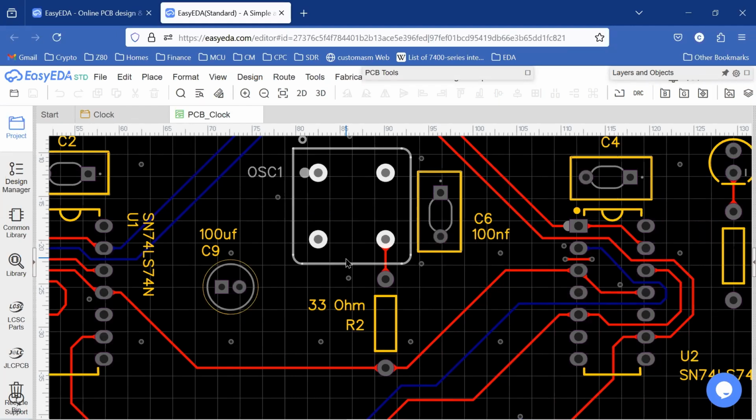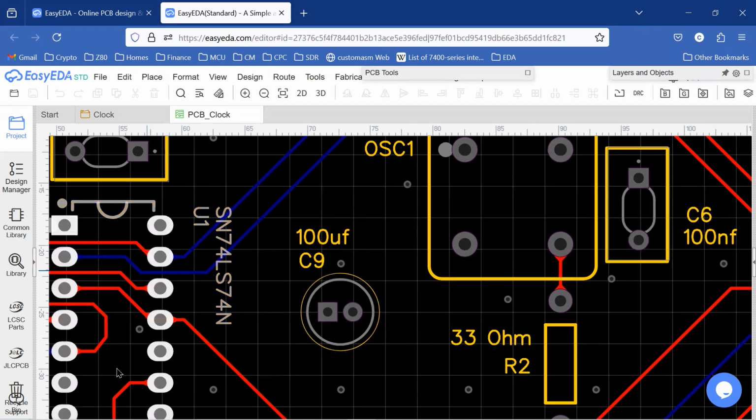So not only do you have to find them, you have to download them in most circumstances and load them into EasyEDA. Now on top of that, I have to really inspect all of these footprints and look at the dimensions for them and see if they are in line with those PCB design guidelines that I shared in the community pages. So that's turning out to not be the case. I'm having to update almost all of the footprints that I pull in. For all of these solder pads for the ICs, I generally had to lengthen these pads. Instead of making them circular, I'm making them oval so that I can increase the width of these pads to have more solder space, but not increasing the width on these, so that there's still a reasonable spacing between the pads.